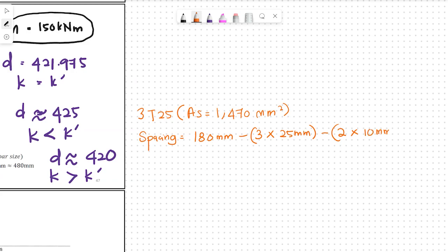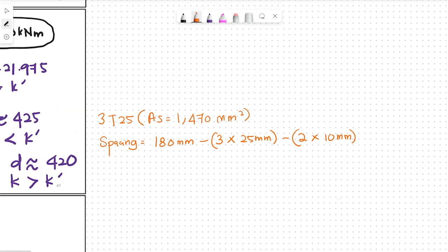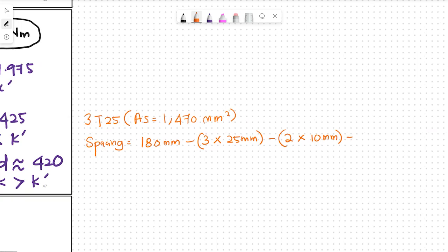So here is my assumption only. Okay, you can assume 8, you can assume 6 lah, tapi this is a normal assumption lah, 10 mm sebab kita tak ada design the shear reinforcement. Normally bila kita design, selalunya saya selalu dapat 10 mm, 8 mm pun ada, tapi because sometimes dia pakai combination of bars. That's why you can get 10mm and 8mm. Tapi you akan ambil the biggest size lah, which is normally akan jadi 10mm juga. So that's why my assumption goes to 10mm.